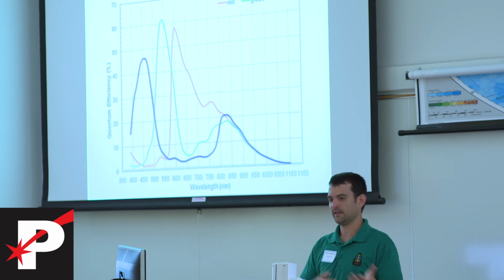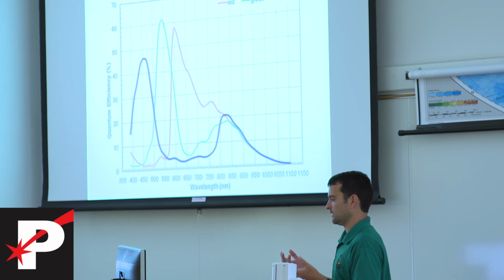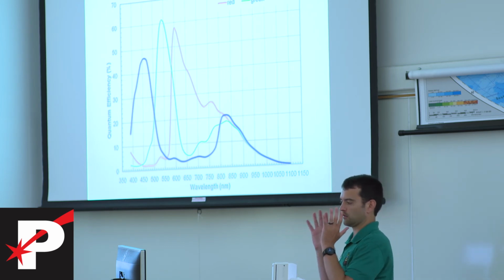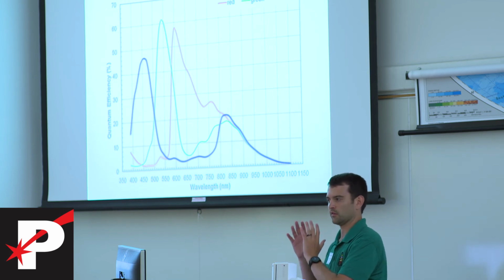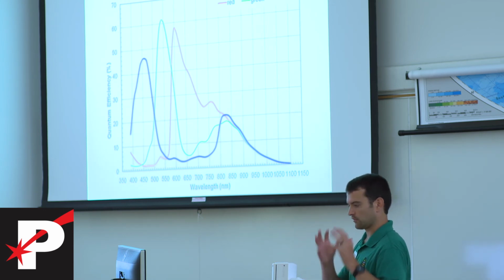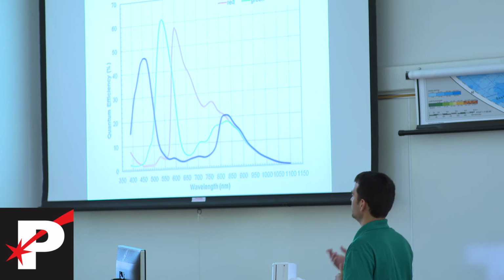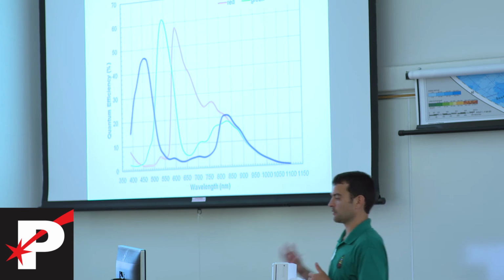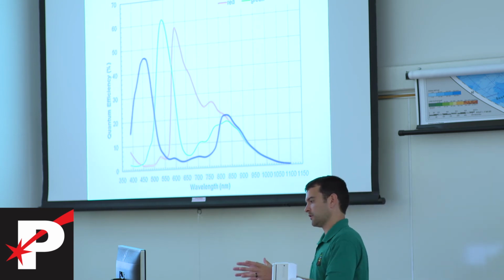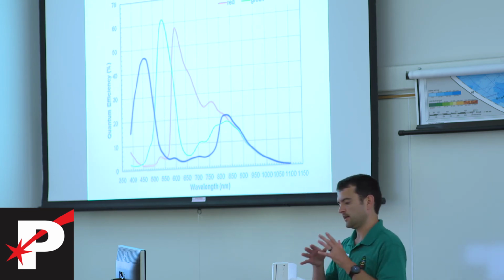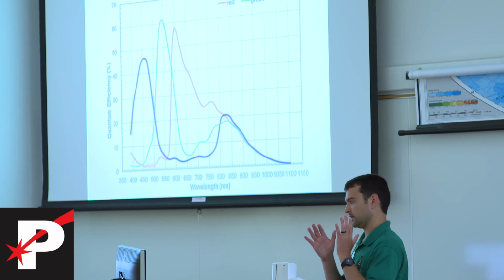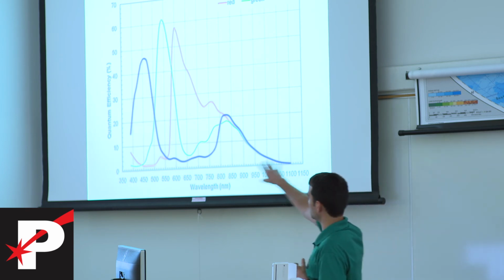of hundreds of dollars. And so what we've tried to do is for the customers that are not looking for the most pure, unadulterated pixel information, they just want good information to start with so they can get an idea of what they're looking at. RGB sensors have been a very powerful tool, and so what we've been doing is coming up with dual band, triple band filters to go over RGB sensors to force the light into particular channels and to try to reduce the crosstalk that you're seeing between these.